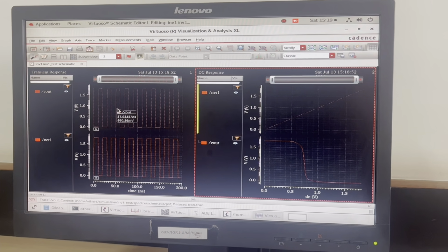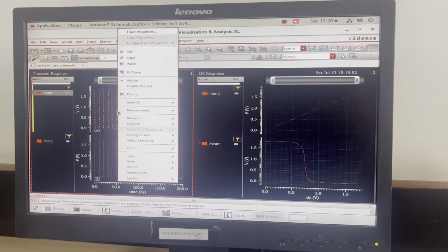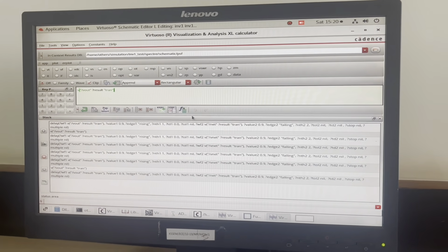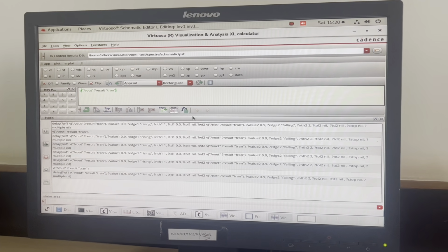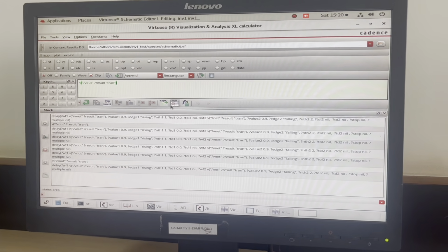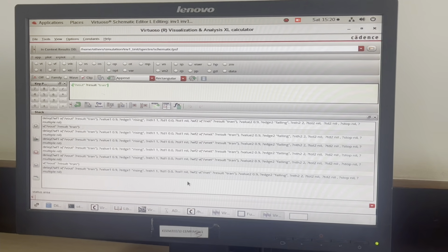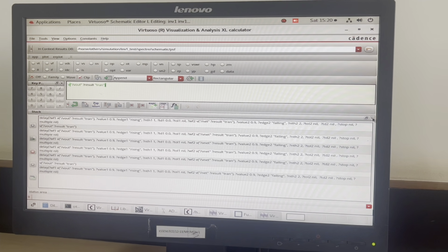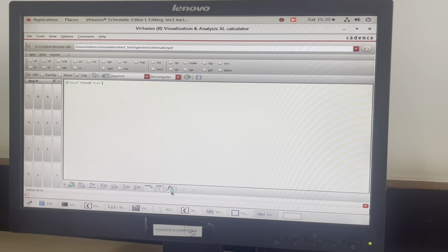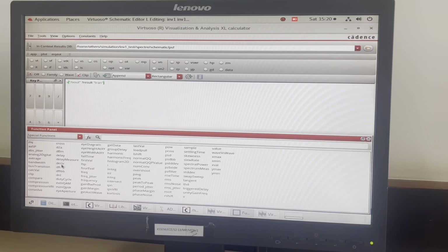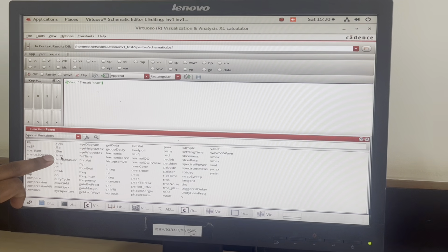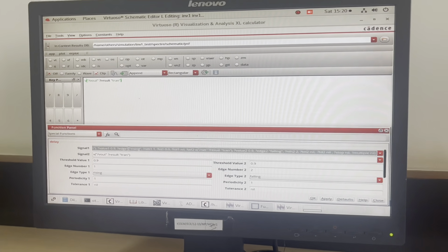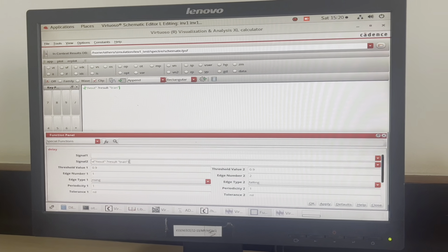For this I will select Vout. On the waveform of Vout, I'll right click, and click on send to calculator. After clicking send to and then calculator, I have to see what comes here. So the calculator window came. The stack will be there, which is not required. You close this. Then here Fn will be there. This Fn you click. And here delay will be there because we need to calculate the delay. So select the delay. Now in signal 1, Control A, delete. Signal 2, delete.